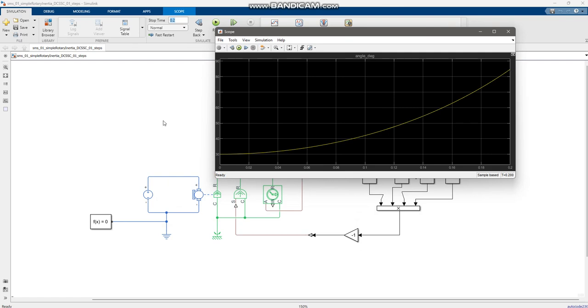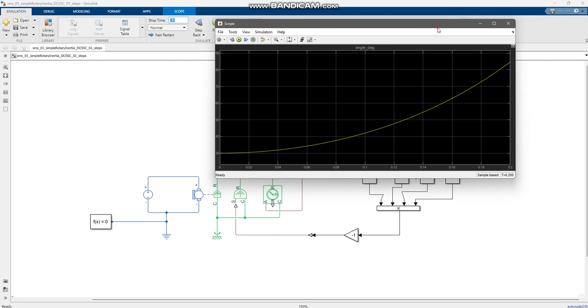If we want the motor to gain a vertical position in a lesser amount of time, then perhaps we'd have to have a motor with a higher torque rating or a higher stall torque, apply the characteristics to this scope, run it and see whether our objective can be achieved. And if we don't need it to be achieved within 0.2, we can opt for a cheaper motor and see what the performance might be.